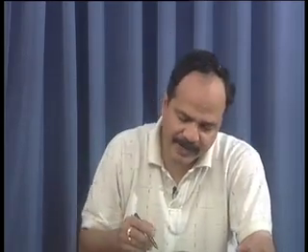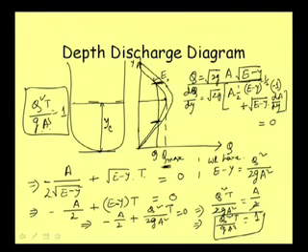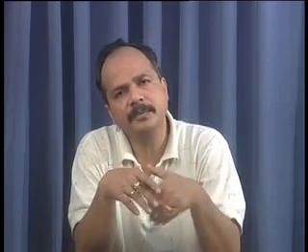Then from this depth discharge diagram we can derive another diagram, that is depth versus unit discharge. Unit discharge means discharge per unit width of the channel. That will come later, and using that relationship we can find out, when a channel is carrying some discharge and is then narrowed down to a particular level, the depth, which was bigger upstream and is coming down as it becomes narrow, so the depth here and the depth on the upstream side will be different.